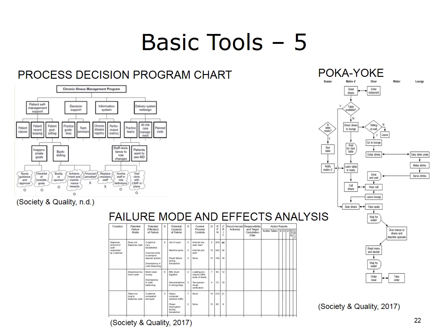Poka-yoke, the Japanese term for mistake proofing, means paying careful attention to every activity in a process to place checks and problem prevention measures at each step. Mistake proofing can be thought of as an extension of FMEA. Whereas FMEA helps in the prediction and prevention of problems, mistake proofing emphasizes the detection and correction of mistakes before they become defects delivered to customers. Poka-yoke puts special attention on human error.